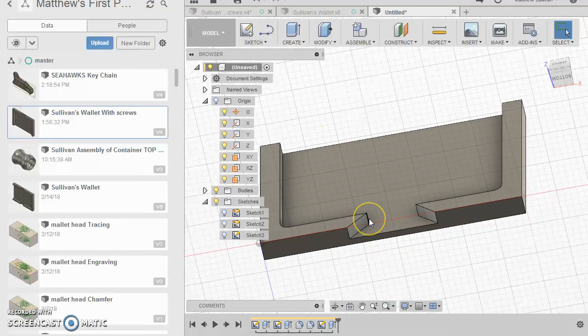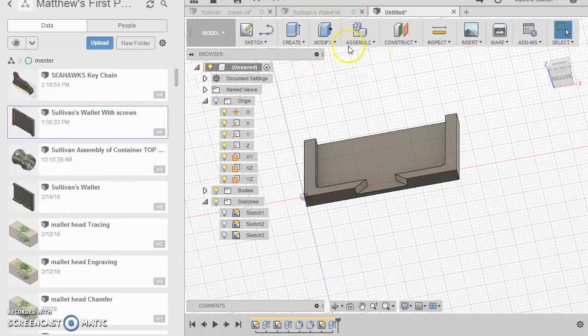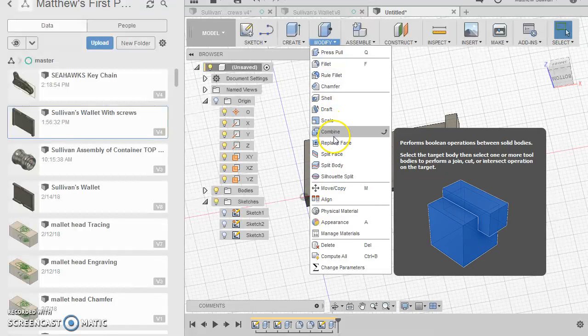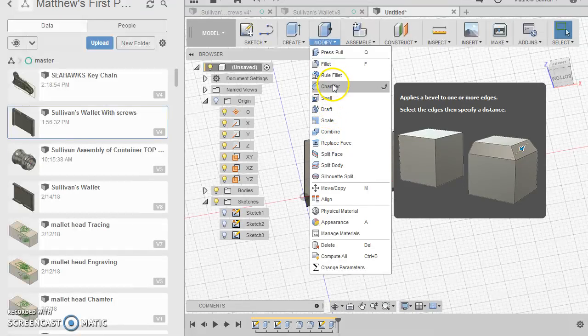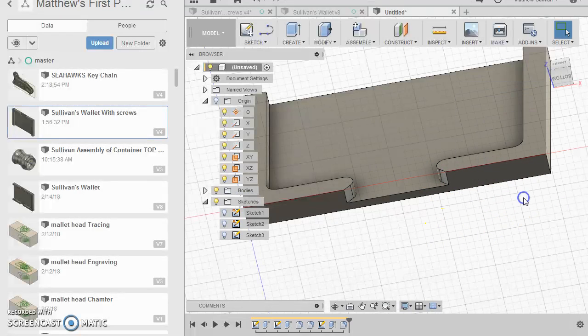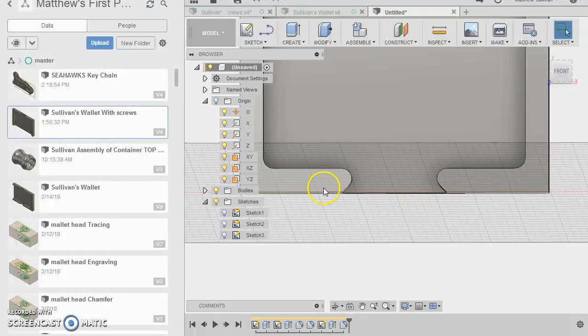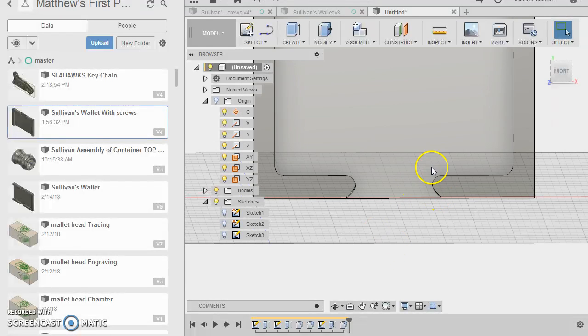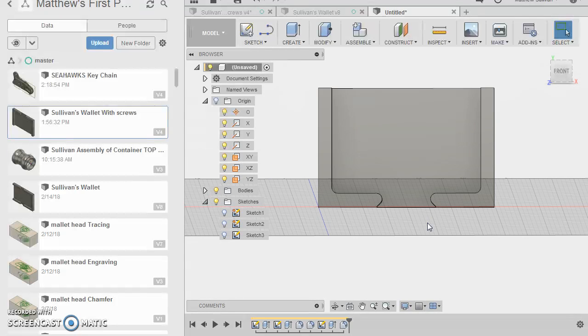I'm not a big fan of these points. I feel like there'd be something where I continually cut my thumb on. If I was pushing these out, I would 100% right away modify these with some sort of radius tool or some sort of radius, chamfer or fillet right here on these 2 corners. And I don't know how big you can make it. You can go like 0.125 and just round them out, because you're going to get your thumb caught all the time on that. You don't want to cut yourself or hurt yourself. So instead of an 1/8 inch radius, if you so desire, definitely have some sort of radius on it, so it's just not a sharp edge.